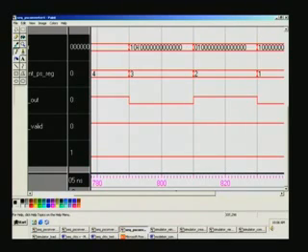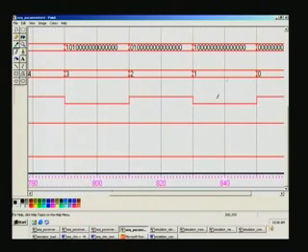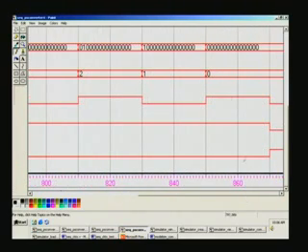You can see here this 0 1 comes over here, and all vacated bits are filled with zeros. Then again this one will go through to the MSB, and again you can see the data out toggling, and finally it lands up at 0 here, and we started with 0 1 0 1 and so on.